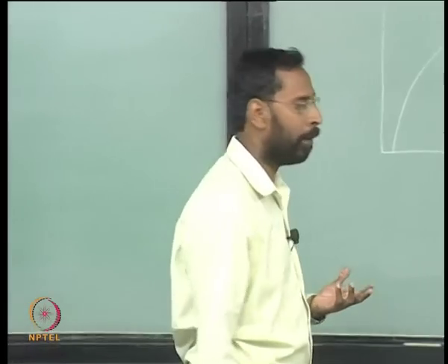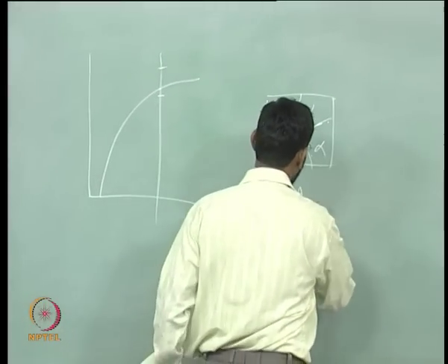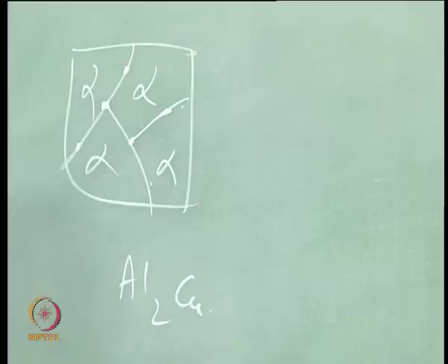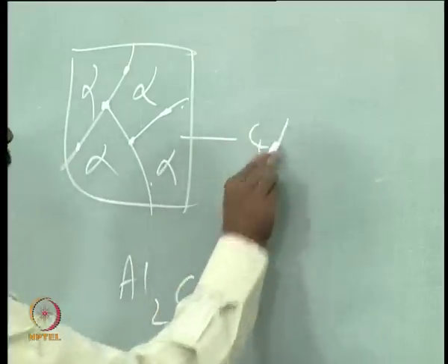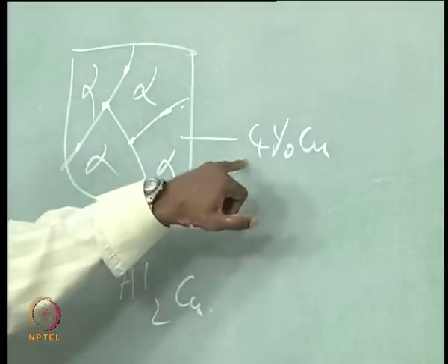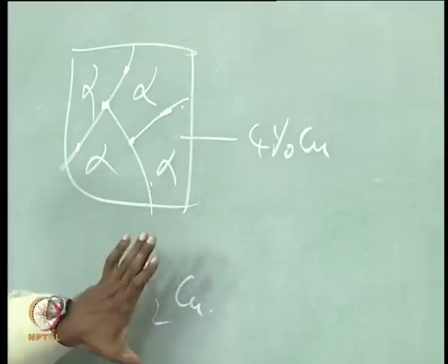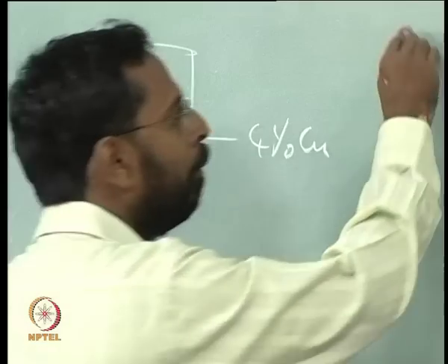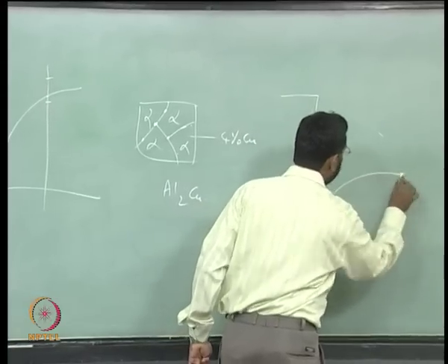the matrix, right. So, Al2Cu is almost 1/3 copper, whereas the matrix has only 4% copper, if I am considering an aluminum 4% copper alloy, which is a traditional alloy. So, if I am considering such an alloy, then if this has to nucleate and grow, you need copper atoms to come from the matrix to this precipitate, and you have seen this happening when we talked about this.